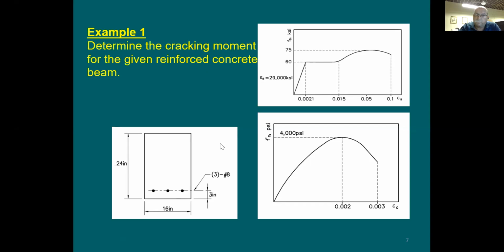Now, my understanding, when I do the analysis for the uncracked section, meaning when I'm trying to work toward the cracking point, the rebars are not going to be triggered. They're not taking any tension force yet. Why? Because if you look here at the stress at the bottom, you're not there yet at the cracking stress. So it's true that the rebars have some effect, but as long as you are below the cracking point, you can just ignore them.